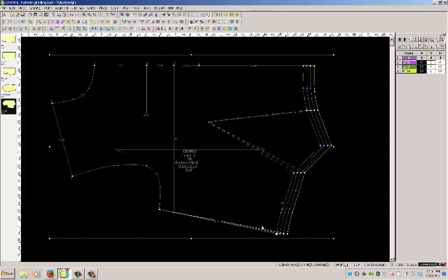Now when I'm at the corner here, this is where you have your circumference grade of 2 inches. So whenever I have 2 inches, half goes to the front, half goes to the back, and I divide by the number of seams that I have. So I have 2 seams in the front. So 2 into 1 inch is a 1/2 inch. So I'm going to type in a 1/2 inch. It's a negative Y because it's going down. So I'm going to type in a negative 1/2.